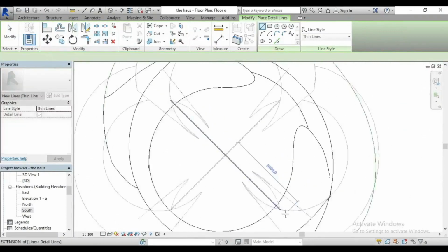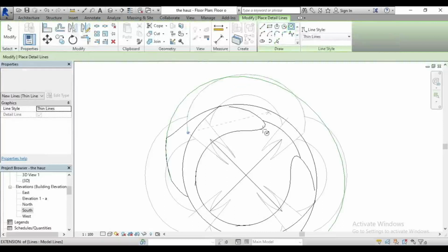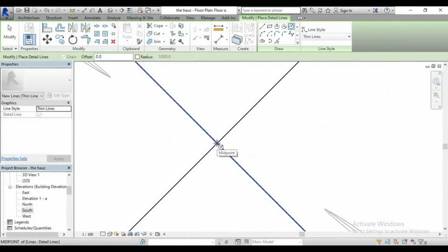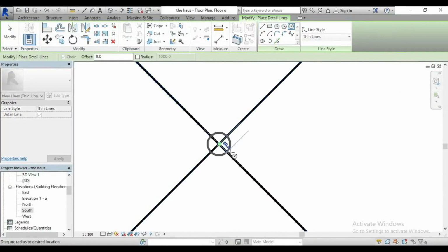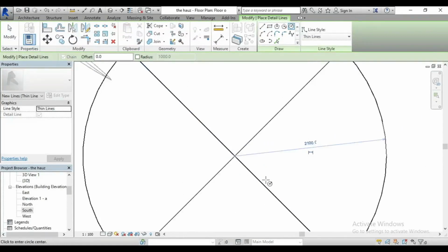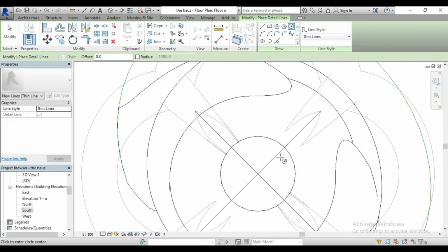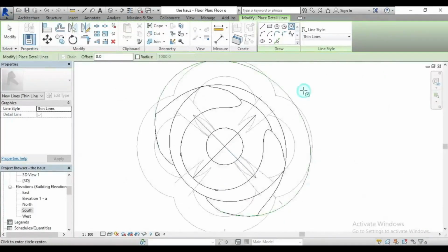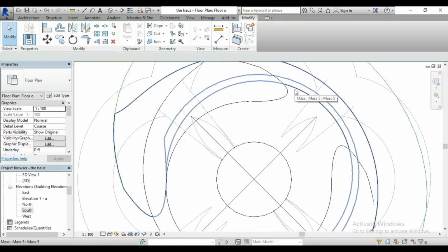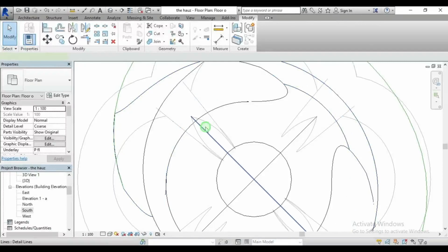And then I'll draw a circle at the middle. I'm trying to create a skylight at this point. So I'll draw a circle to represent that skylight, let's say with a radius of 100. Okay, so this is how big my skylight will be. And then around it, I'll just have a dome, a rising kind of dome, like a roof structure.